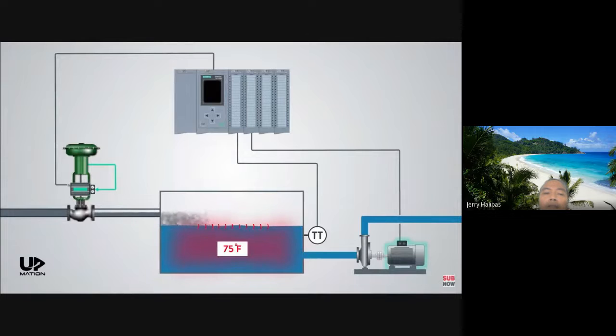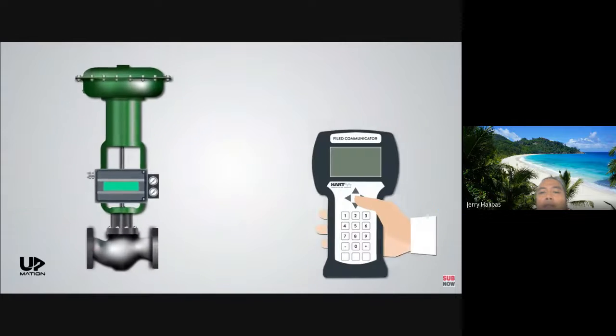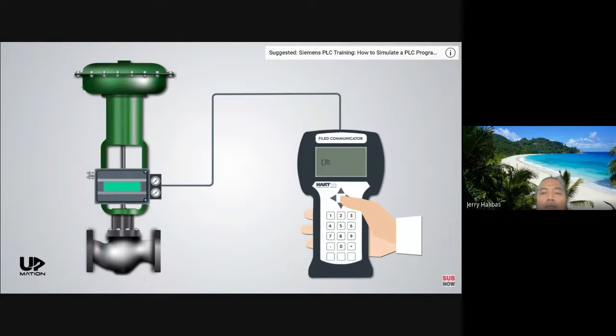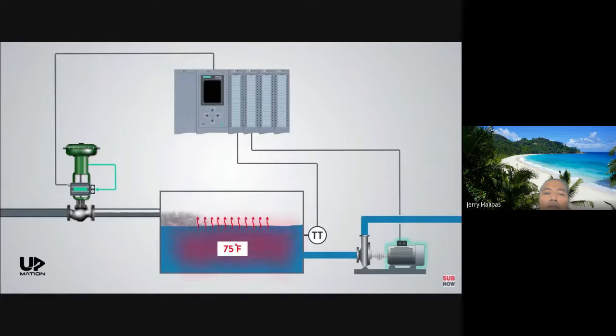Using digital positioners, we are able to communicate with the valve by different types of protocols, such as HART or fieldbus protocols like Profibus. By such digital communications, we can calibrate control valves way more easily using handheld communicators without tackling time-consuming and sometimes difficult mechanical adjustments. Besides, we can send some feedbacks from the control valve to the PLC or DCS via these communication protocols.